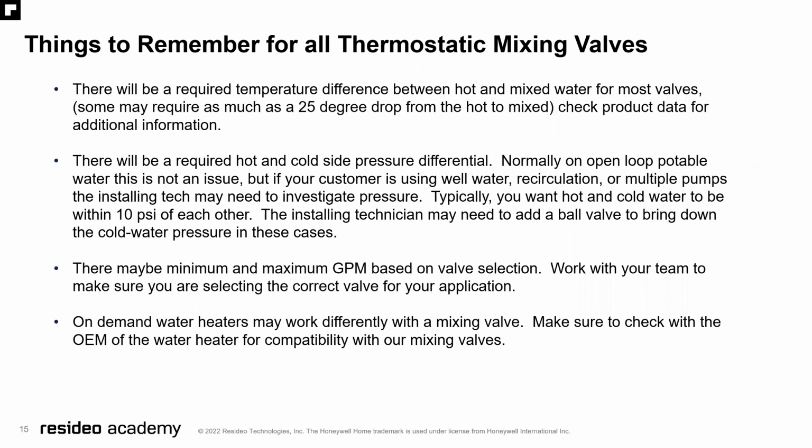Some things to remember for all thermostatic mixing valves, and these have been kind of curated by the questions that we get on the tech team. There will be a required temperature difference between the hot and the mixed water for most valves. Some may require as many as a 25-degree drop from the hot to the mixed, depending on the rating of the valve and style of the valve.